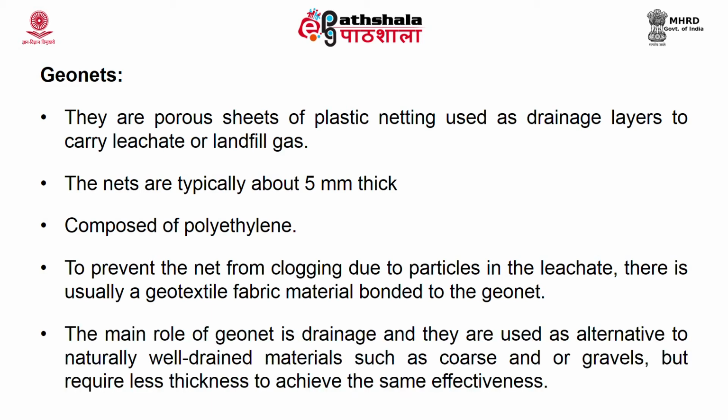So, the main role of geonet is drainage, and they are used as an alternative to naturally well drained materials, that is coarse gravel or sand. And though they are used to replace the well drained materials like coarse gravel, they require lesser thickness when compared to coarse gravel. So, that is more effective than coarse gravel.